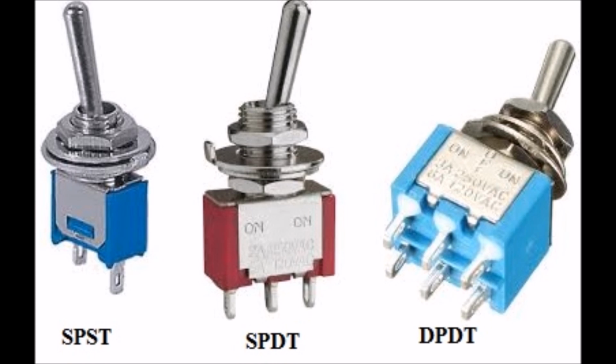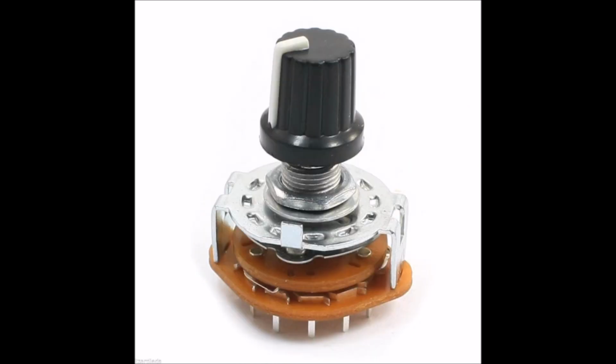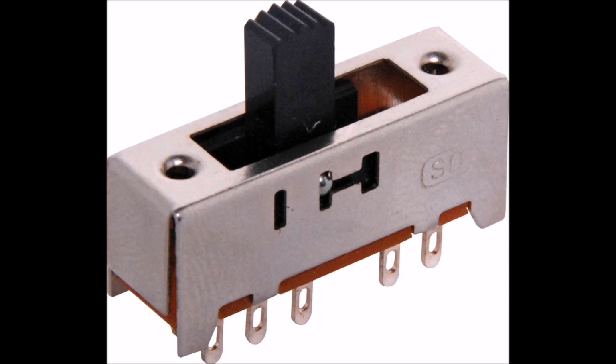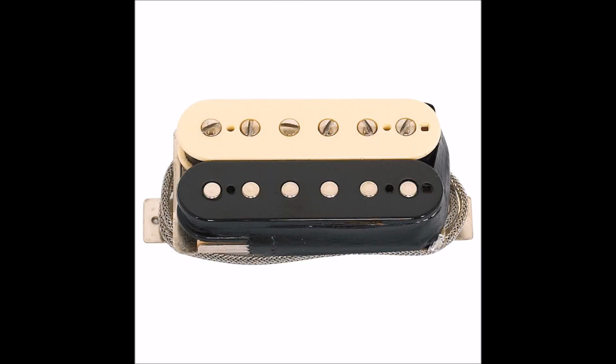In this simple 2-pickup setup, using 2 identical SPDT switches might be a better option, in order to have an identical physical or tactile feel to the operation of the switches. Another option would be to use a 2-pole, 4-position rotary switch or slide switch. This switching system for 2 pickups may be useful in switching humbucker coils, combined with other switching schemes.